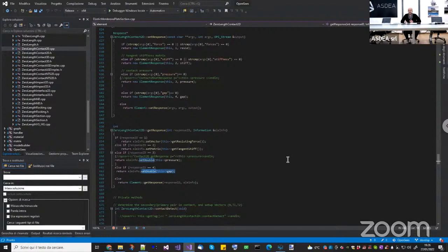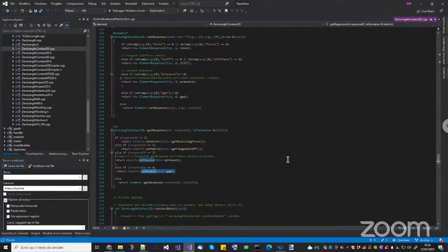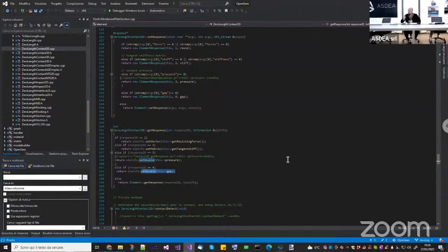Can you explain? Basically, in STKO, when you are giving the mesh, it can generate the mesh automatically. But if you want to do it manually, when you are creating some interface between the soil and concrete, there we have to give different node tags to create the contact, or we have to give the same nodes to create the contacts. Probably you mean, basically, okay, let me see if I understand.